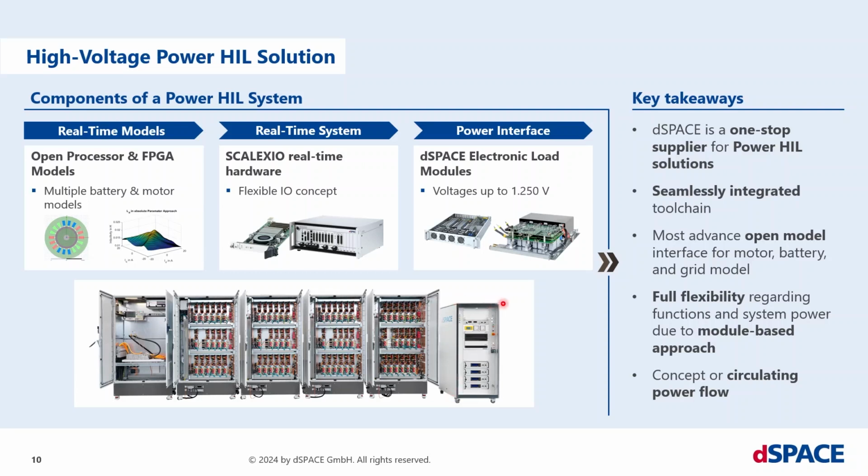The uppermost right cabinet is more or less the brain of the overall system. Here's the Scalexio unit placed. So here's where the real-time models are running. We have a high voltage power supply here. We have low voltage power supply, some safety functions like isolation monitoring. But the main part of this cabinet is that all the Scalexio units are placed there and you can run here your real-time models.